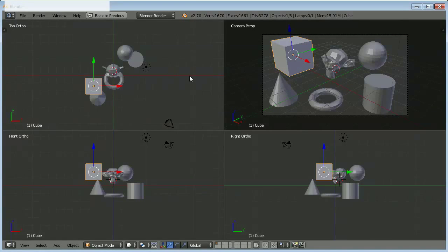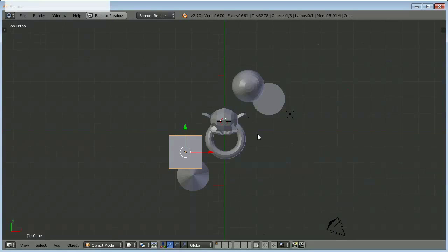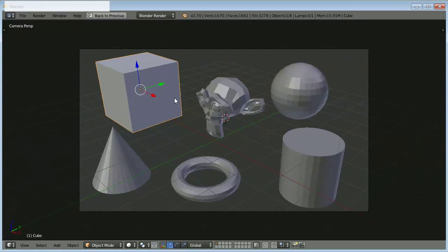And the other thing the instructions ask for under task 2 is to provide a render of the scene. So if I come back out of quad view with Control Alt Q, again I've clicked on something else, so I have to click back on Blender for this to work. Control Alt Q, and that's dropped me into the top ortho mode because that's where my mouse was. I can click numpad 0 to get back to the camera view.